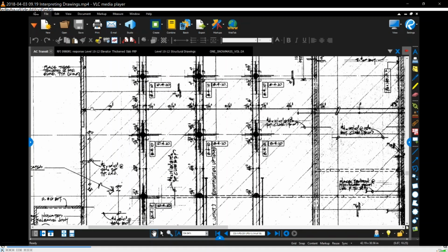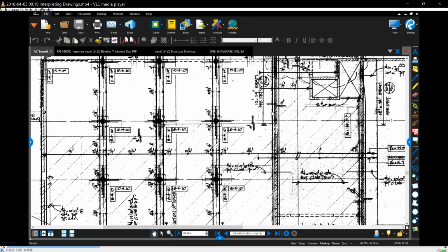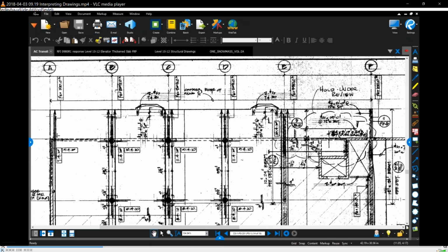I should also let you know, when the tendons have this kind of extent line on them, those are called uniform cables. These are spaced in order to get an average compressive stress of 12.8 kips per foot of width. They are uniformly spaced along this slab edge, and they span over banded cables, or groups of cables, that are provided over the columns. Those have a total of 205 kips for this particular banded cable grouping.